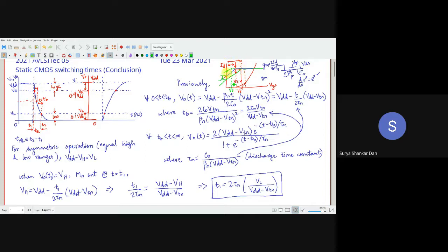So what industry needs to do is ensure that the battery should last for at least 2.5 hours or 3 hours when you are purchasing a laptop. So instead of using the actual threshold voltage, they will estimate how much reduction in the threshold voltage will happen and how much off current the CPU can still kind of survive, let us say. It can still withstand. Okay. So they'll rather overestimate the threshold voltage by a certain amount, so that even if you are watching, say, a very long movie,